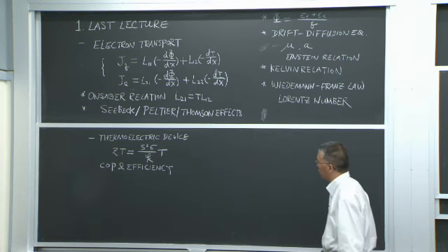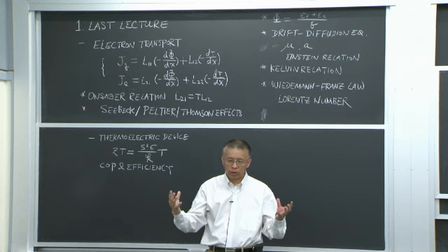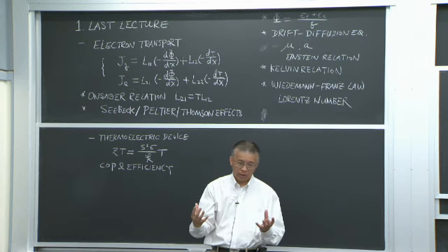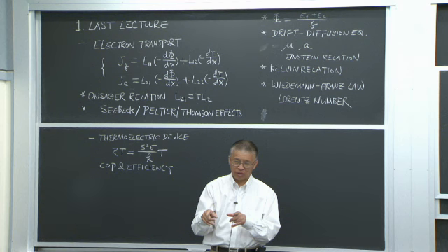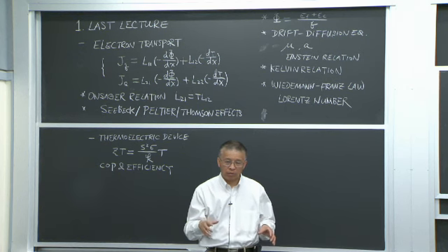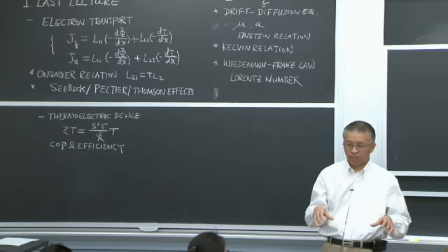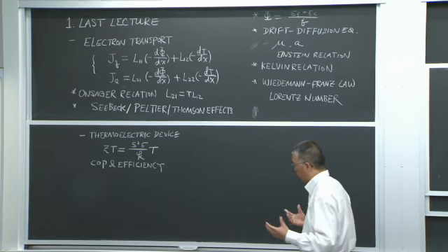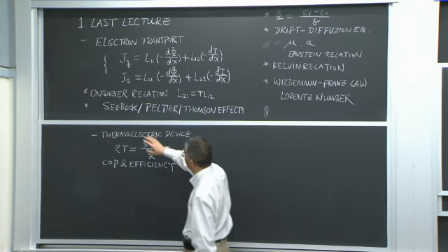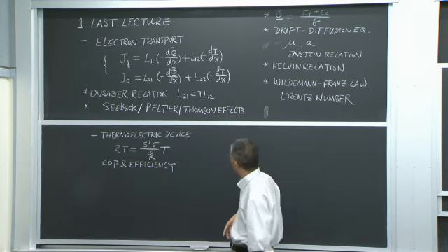And that's the Peltier heat, which manifests itself when you put two materials together and form a junction. And because of discontinuity in this Peltier coefficient, you have cooling or heating at the junction. But fundamentally, it's an effect that happens in the same material, right? So we talk about the material properties: Seebeck coefficient, Peltier coefficient.